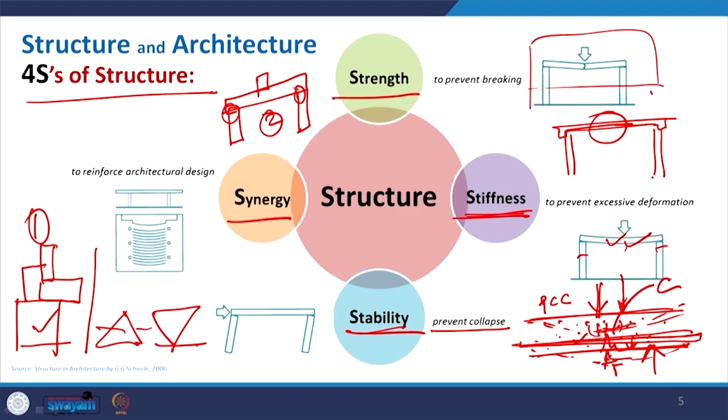In that case, those joints are very critical, because here you just represent it in the real case. This is a slab and this is a beam, or there will be some column, and those joints should be cast adequately. Proper care should be taken so that during that movement this structure will act as a monolithic structure.